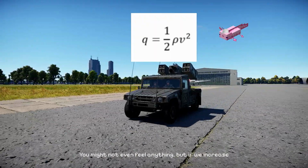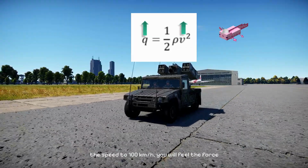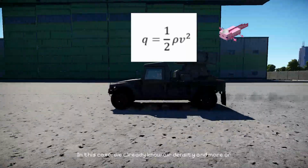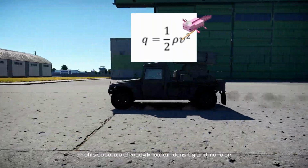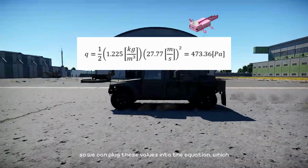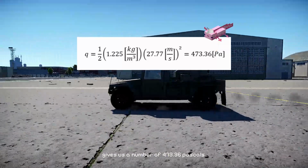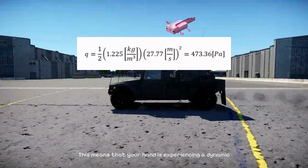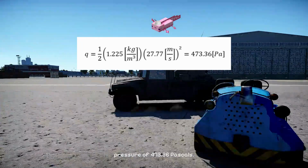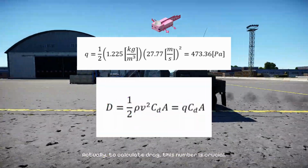You might not even feel anything, but if we increase the speed to 100 kilometers per hour, you will feel the force increase. We can actually use dynamic pressure to quantify that force. In this case, we already know air density and more or less the velocity of the fluid, so we can plug these values into the equation, which gives us a number of 473.36 pascals. This means that your hand is experiencing a dynamic pressure of 473.36 pascals. Actually, to calculate drag, this number is crucial.